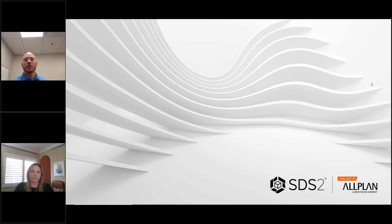So one's asking about the extents of the views and how those are created. In the webinar, you remember, I can isolate those connection cubes and adjust the views for my 2D detail. So that's going to affect the creation of that 2D detail. I could adjust depth check, extend that, add views, whatnot. Right now, the size of that cube will stay standard.